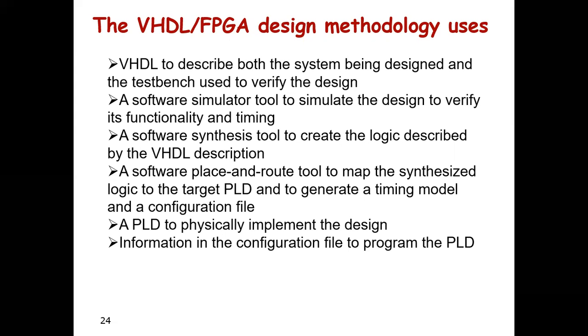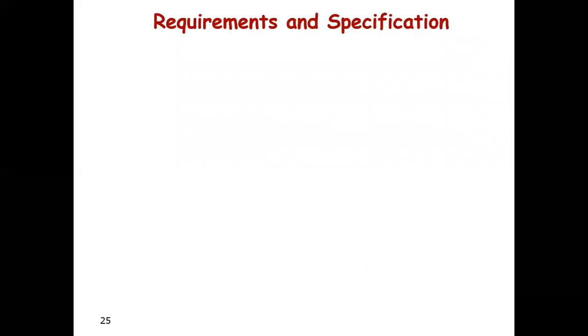A software place and route tool to map the synthesized logic to the PLD and to generate timing information and a configuration file. A PLD programmer to physically implement the design, using the information in the configuration file to program the PLD.